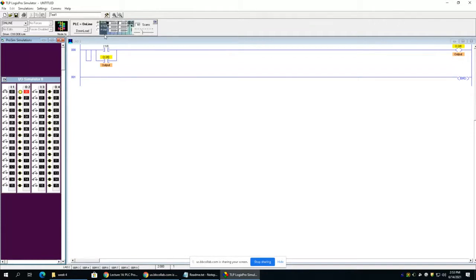What if you have something in between the contacts and the close position? You can't close the button. It could be something stopping the button from closing. I guess in theory it could be something to stop it from opening. But by OSHA rules, your physical stop buttons are always normally closed. So I'm going to go in here. We got to put the stop button in here, and we'll use this one as a stop button.